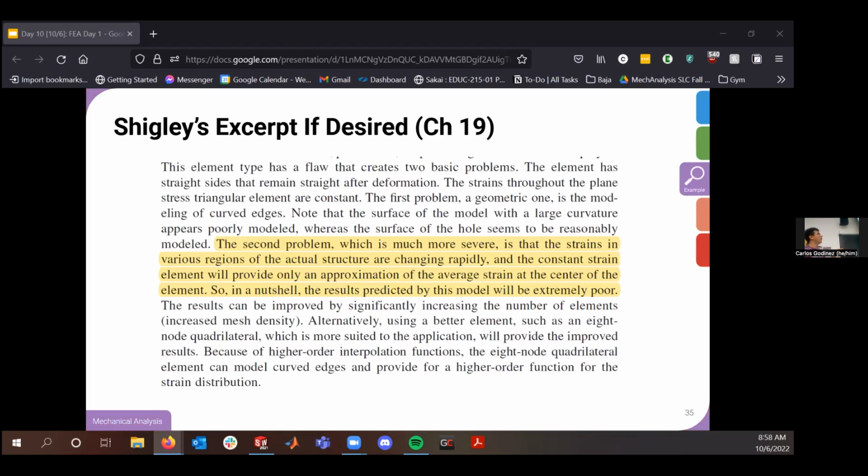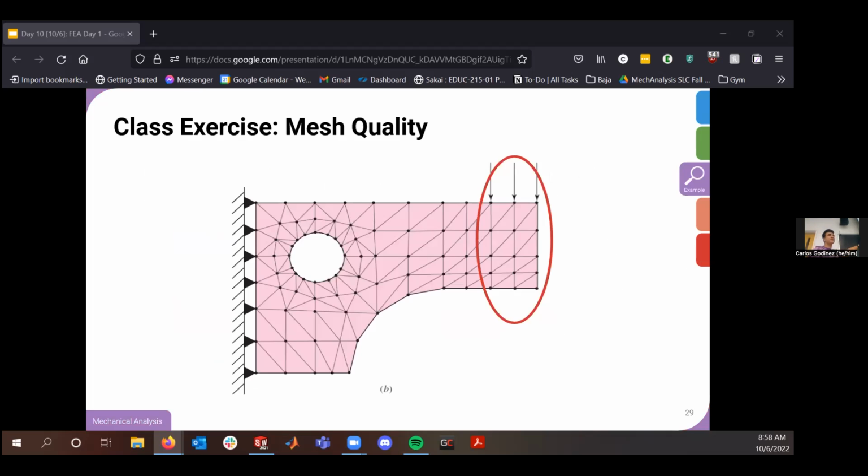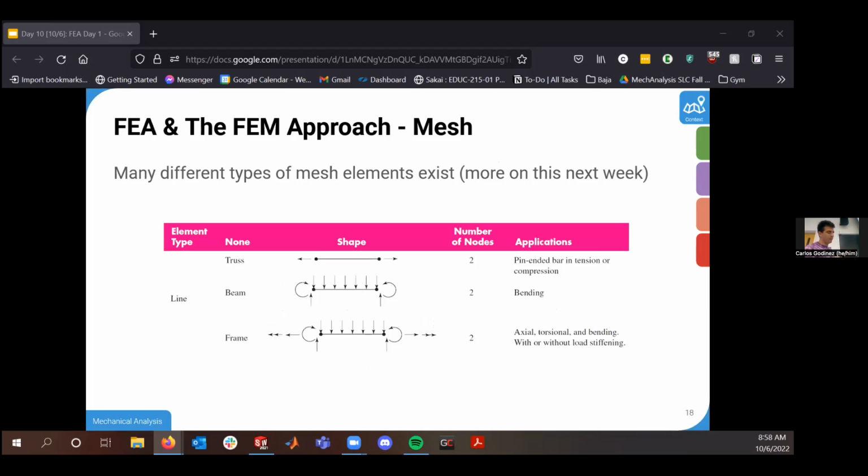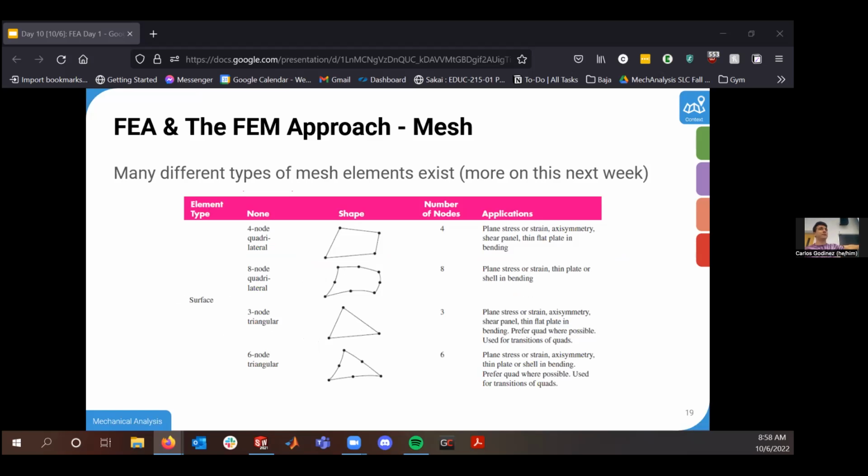That's a great question. For this specific case, no, actually. This goes back to all the way over here: there are different mesh types. The line truss is just a 2D case where you have length and translation. This is a surface mesh, meaning I can approximate this flat plate as a surface, and in my solver I can assign a thickness that it uses for calculations.